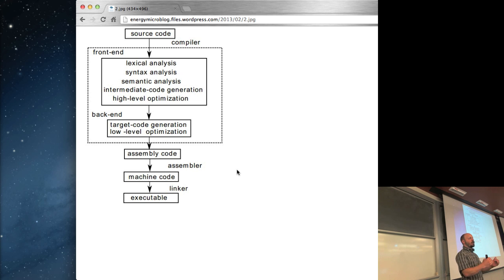So if you write C code, there really is an equivalent to what you write in C to what you will later on see in assembly. Now, depending on what level of optimization GCC does, this can be almost unrecognizable. Or sometimes it disappears because GCC recognizes that some of your assembly code was not written very well, or it did something that was not useful, and so it just removed it to speed up the process. Now, in embedded systems, this can oftentimes be a big problem for you, because sometimes you do things that the optimizer doesn't know or doesn't understand that this is really what you want to do.